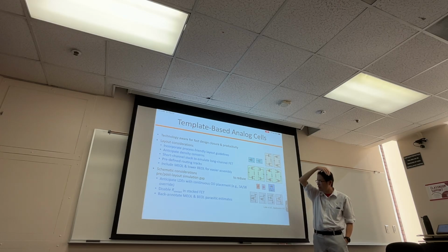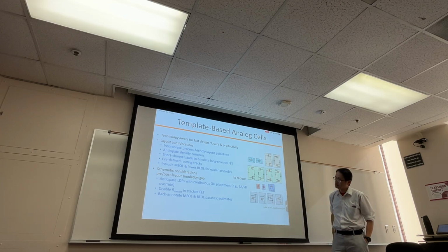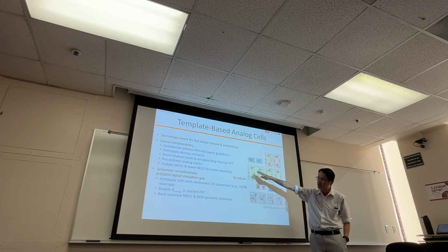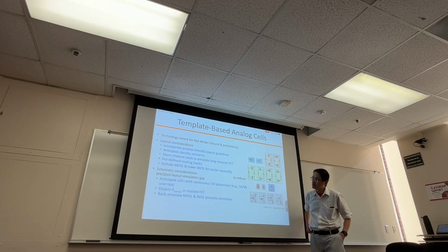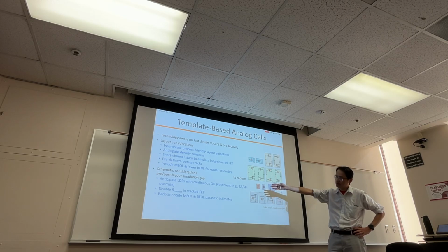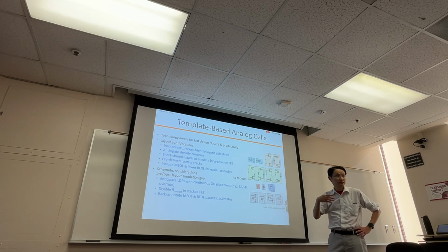So yeah, similar thing here. You do more of a module approach, even in the analog sense. Okay, and not only can you consider the density, basically those DRC tracks, you can also look at, remember we talked about this LDE effect, layout-dependent effect.